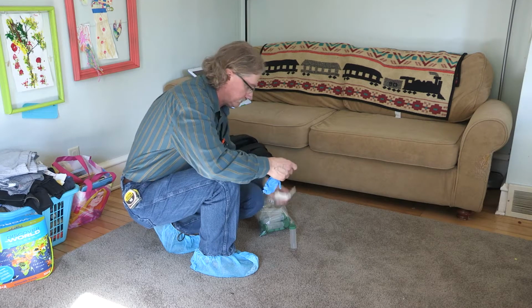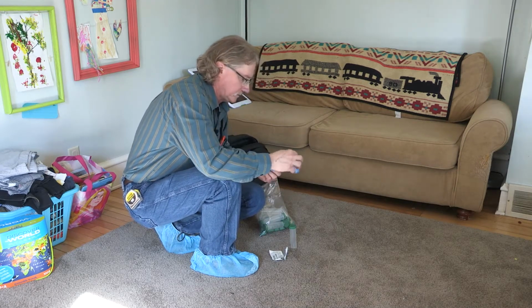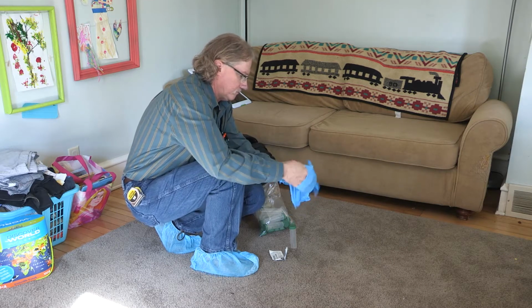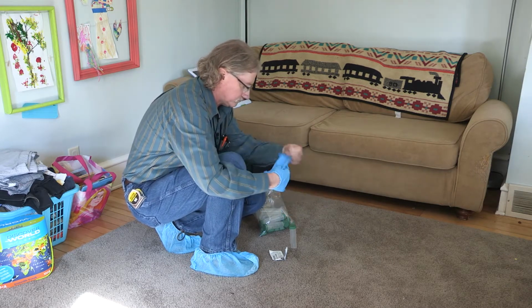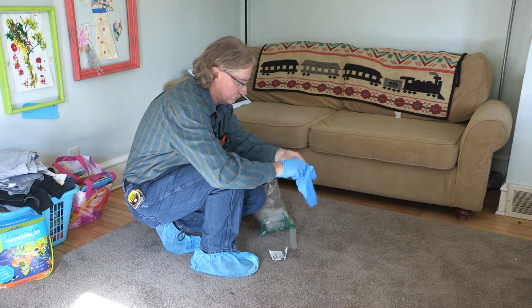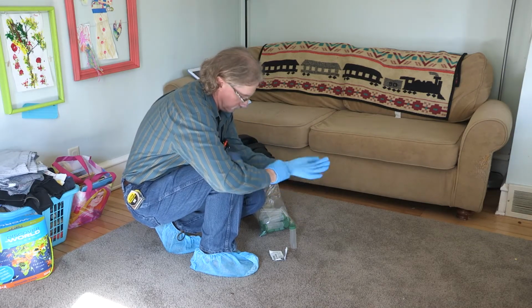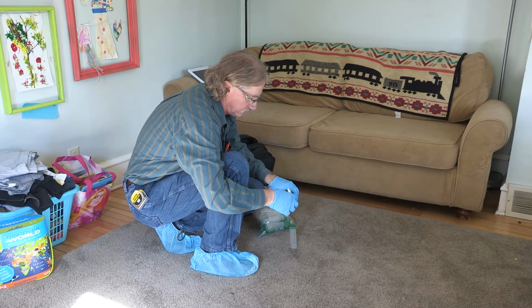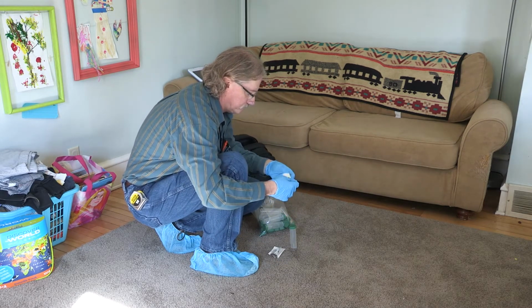For quality assurance, 1 field blank is required for each dwelling tested. To prepare a blank sample, put on a clean pair of gloves and fold a new, unused wipe to look like other wipes you collected. Place it into a sample tube and label with a sample ID number. This ID number should correspond to an anonymous location you assign on the chain of custody.